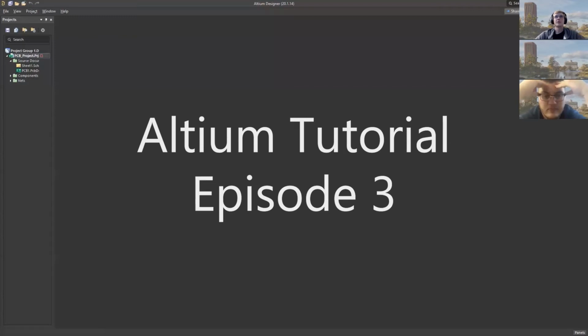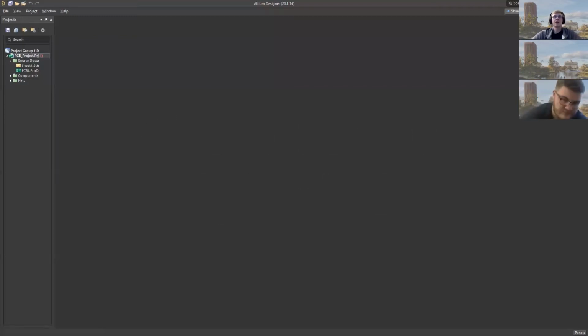So this video is going to be similar to the last video, except I'm going to walk you through the actual PCB editor. You will recall that last time we were talking about, all right, well, if I just want to make a PCB, why do I even need to bother making a schematic? And the reason is that the whole point of Altium is that it's constantly checking what you're doing. So you're setting up rules, you're making promises to Altium, and then when you go to actually generate a circuit board, Altium is going to make sure that you are staying true to your word. You're connecting the correct components together, which you specified in your schematic, and you're within a bunch of constraints.